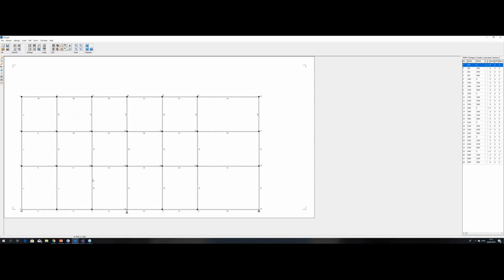Normally, this is a stringer model. We have also panels here. We will put in some panels here with a window here and a door here. But remember, the loads from here will not come down in this panel here, they will go to the node and then down here. So if we want to make sure that some of the load goes down here, we add an extra stringer here. Not here, it was here, and also here.